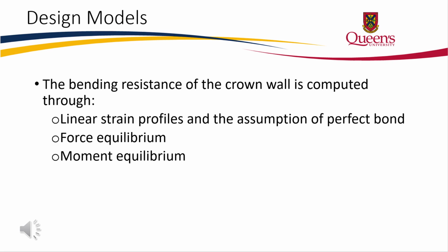The design model is solved iteratively with different liner thicknesses until the system avoids cracking strains in both the liner and the concrete.